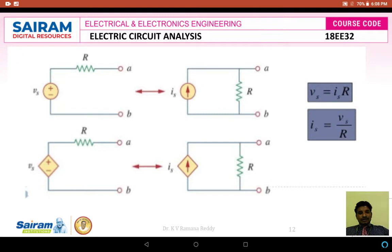So the figure you are seeing here is a practical voltage source, represented by Vs, and plus and minus are the polarities for this practical voltage source, and R is the internal resistance of this practical voltage source across the terminals AB. Now I am going to convert this voltage source into a current source.